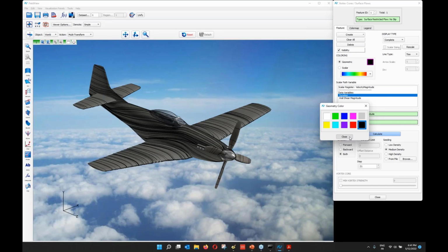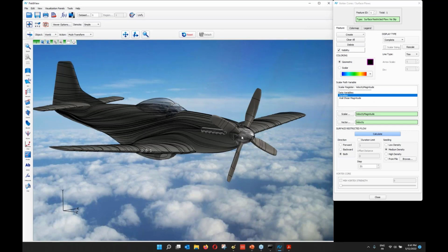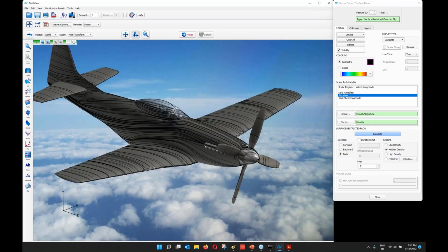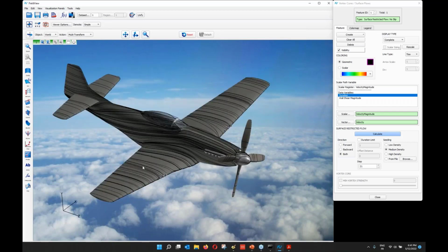And here you can see our friction lines with some rotation being used by the propeller, and also you can see the different aspects of the flow. We're not running a very accurate simulation, and we don't have a high angle of attack in this case, so you're not catching separation on the wings, for instance, but that will show up with such friction lines.